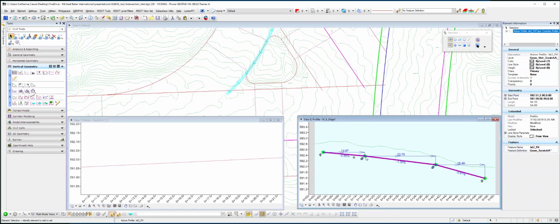You can kind of see what this vehicle is going to be experiencing if I maintain set slopes across that in order to make sure that I, one, have drainage, and two, have ADA compliance or sidewalk ramp compliance, where they fall within here, which is at 1.3%. I know I've got a nice flat surface here that's going to work for those sidewalk ramps.